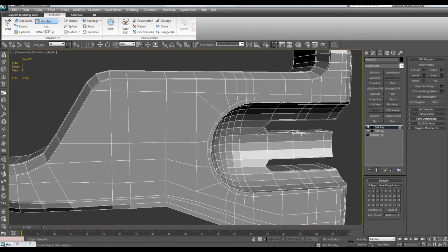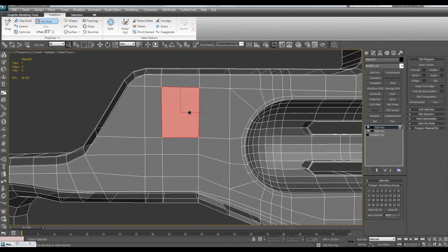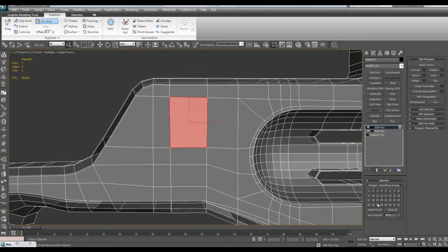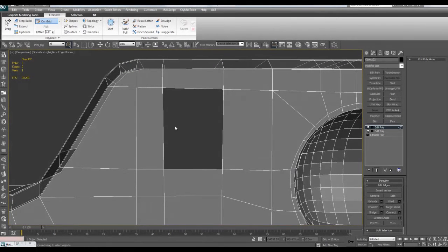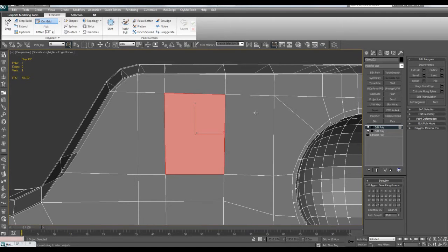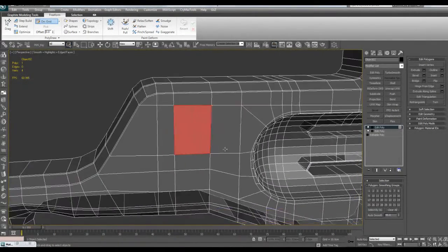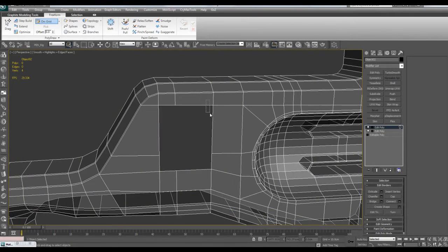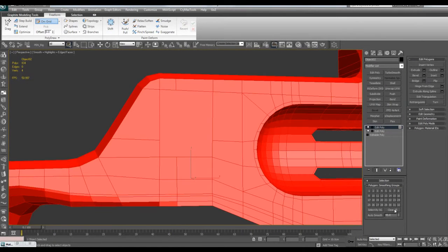And 3ds Max also has an annoying habit of automatically creating smoothing groups. So if I delete this, you can see right now this polygon has a smoothing group of none, 0, it doesn't have any. If I delete that and use the bridge operation, then click on this polygon, actually right now it has not created any smoothing groups, but sometimes when you perform various operations like a bridge, or maybe the border, it will.